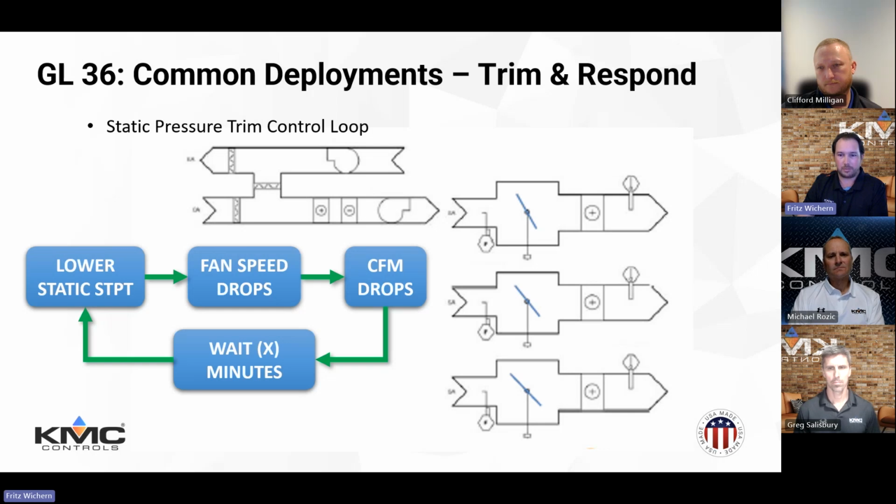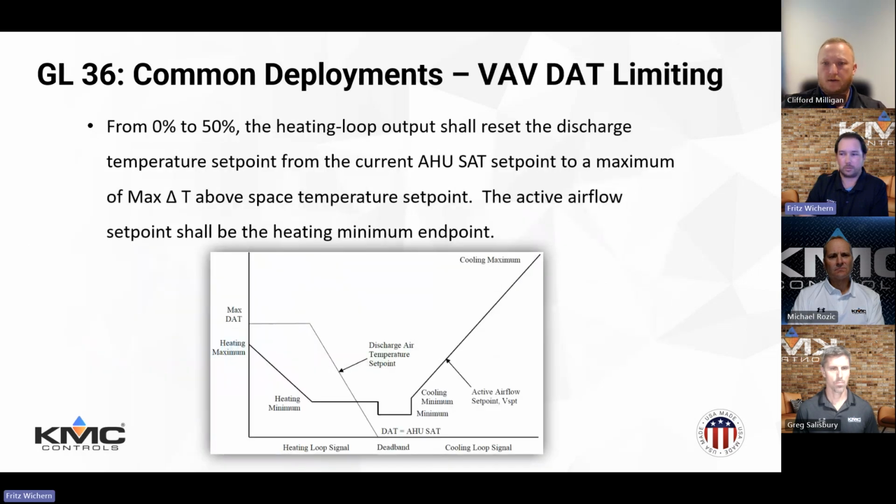It's important to make sure that you have all your VAV boxes sending the right data. You're pulling the right data to your air handler. I think maybe one advantage in this case is using IP-based controllers. Get you a little faster response versus MSTP. All right, so we'll look at VAV discharge air limiting.